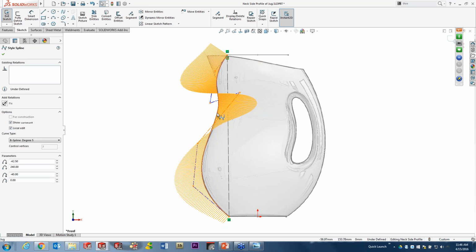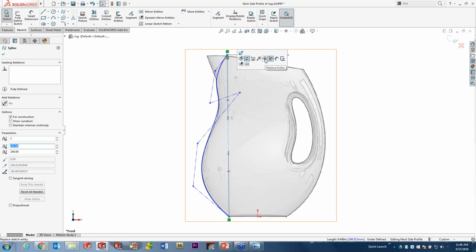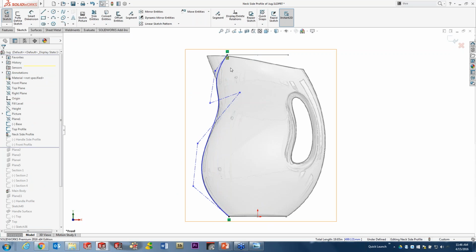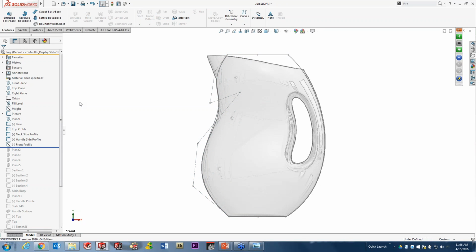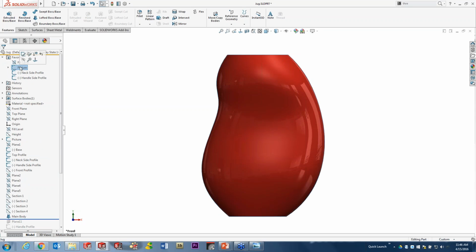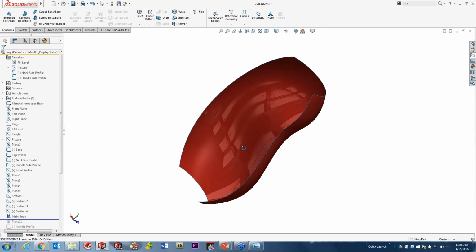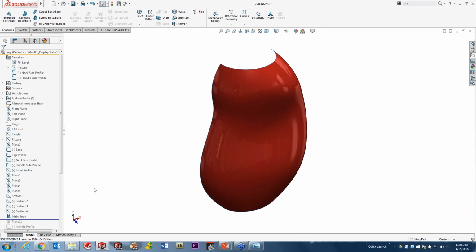Looks great. So I'm going to go ahead and take that spline, and that's going to be my input for the side of this surface. So let's just go ahead and do that. Now once I finish up this sketch, we're now just going to go down halfway through this part just to show you the other surfaces that are built up here. And there's a few other things we don't need to see moving forward here, so I'm going to hide these. But essentially what we've now got is we've got this surface body that we used from sketch on one side to the sketch on the other.